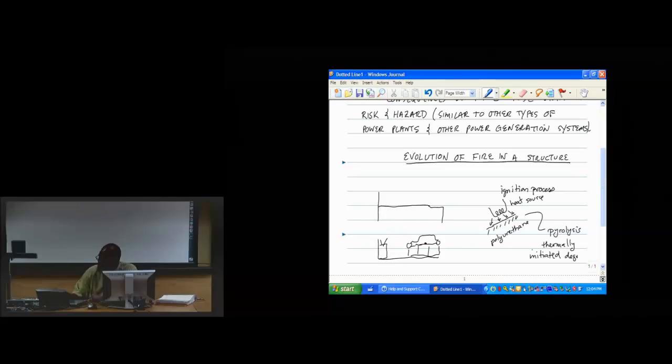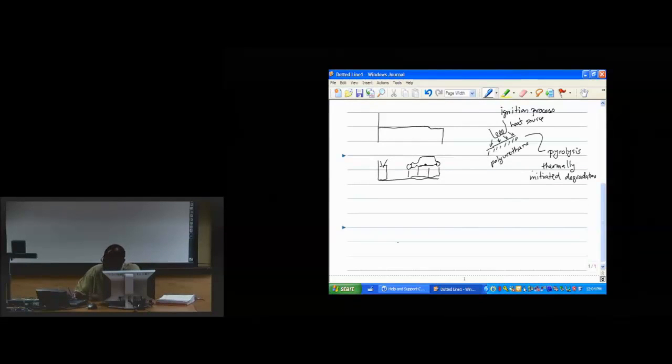And what happens is that we release small fragments of smaller molecules that percolate through this porous medium, this polyurethane, again, because of the heating. So now we're going to draw this a little bit differently. We have this heat transfer process. We're going to use the notation Q dot double prime for a heat flux, the units of which are watts per meter squared.